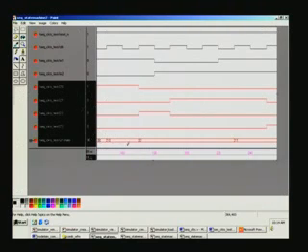And in the S2 state, although it enters the state right at this positive edge of the clock, the actual lamp output will go only at the next positive edge of the clock right here. So you can see for S0, and this is S2 here, right? This corresponds to the S2 state, and so on it goes.